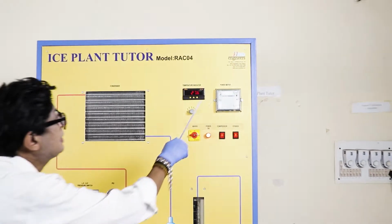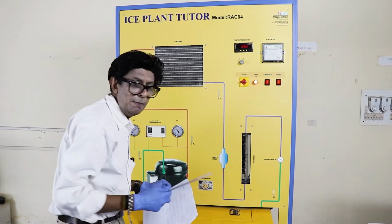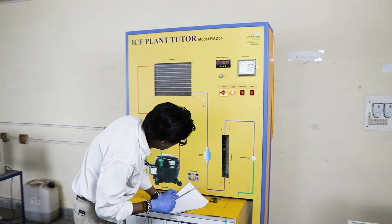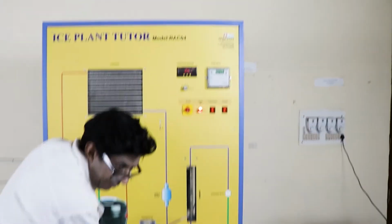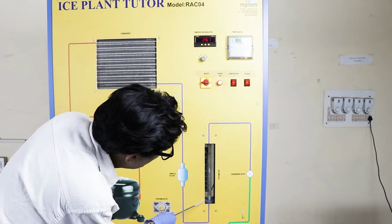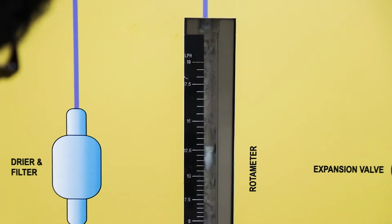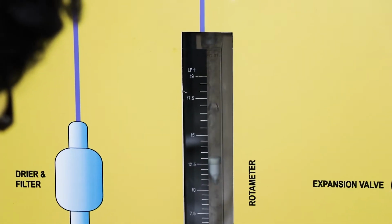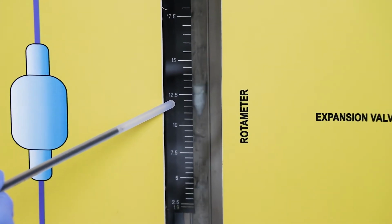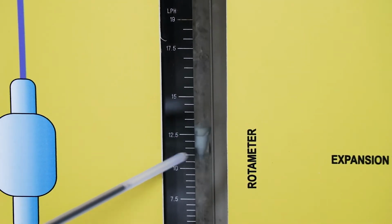We will not read this power meter reading, because we will find the work of the compressor with the help of the equations and the pH chart. Now one more reading is left out, which is the reading of this rotameter. This is a flow measurement device used to measure the flow rate of the refrigerant. Refrigerant is coming from the bottom side and applying force on this float. This white thing is a float.